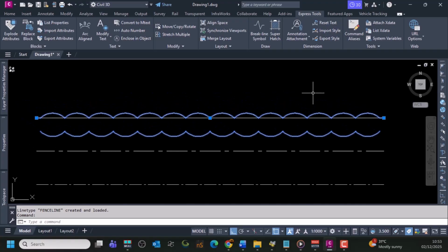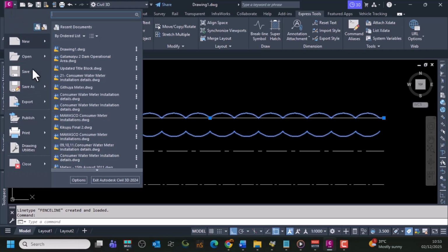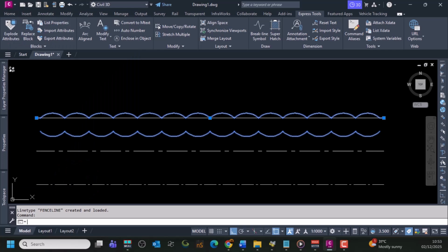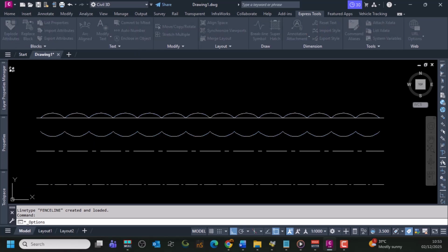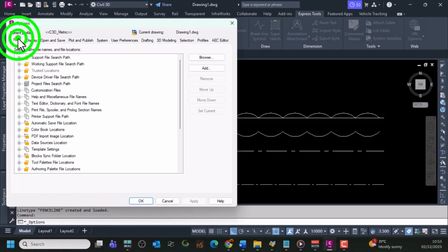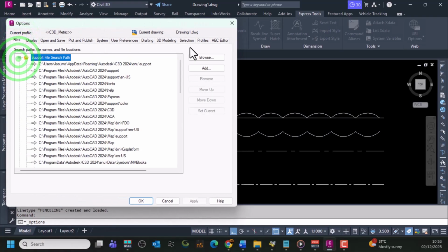The line type we have defined can now be applied to drawing items and layers. In order for line types using shapes to work properly, both the .lin and .shp need to be in a support file search path, such as the location of your acad.lin file. If you ever need one of your custom line types in another drawing, just type in linetype and select the Load button.